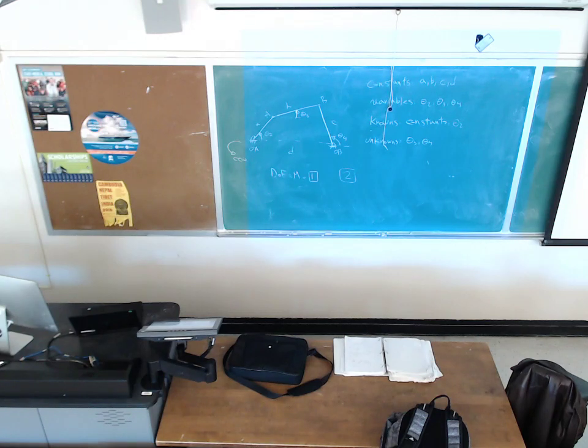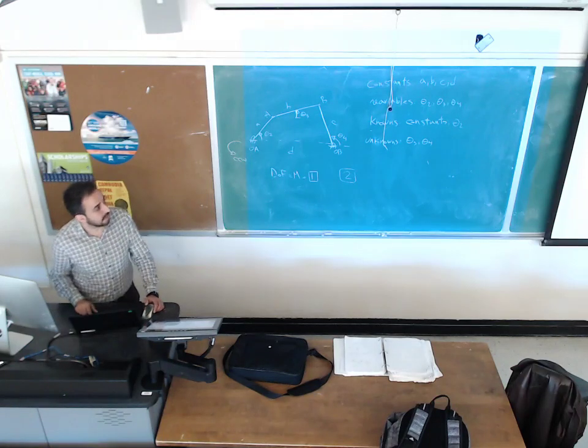But what I'm looking for is the angle of theta 3 and theta 4. You should measure by drafting instrument, measure this angle and report this as theta 4. And measure this angle and report this as theta 3. So with the graphical approach, you can just say theta 3 equals whatever number comes from the measurement, and same thing for theta 4. So this is what you need to do for 4-bar mechanism displacement analysis with the graphical approach.